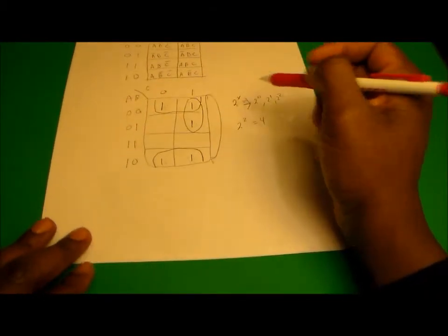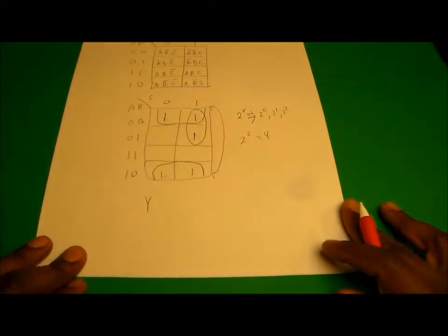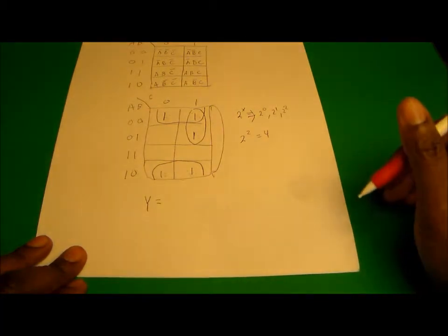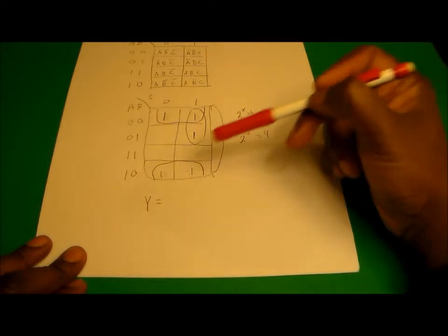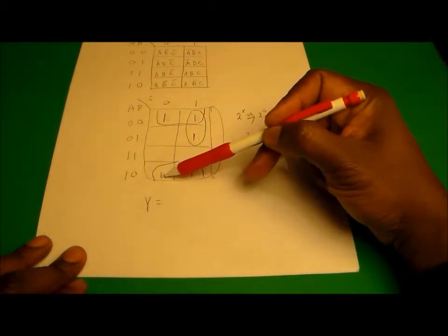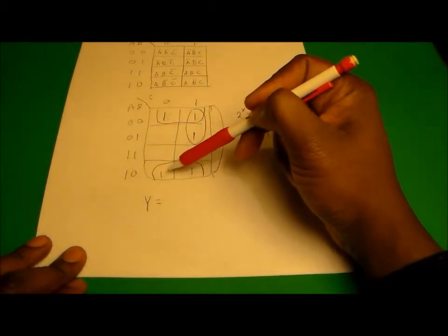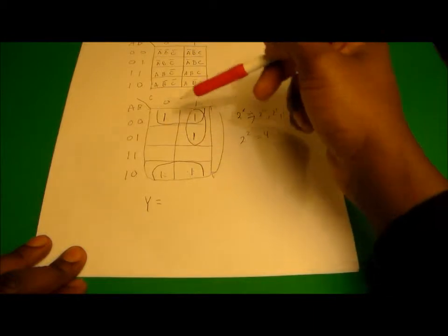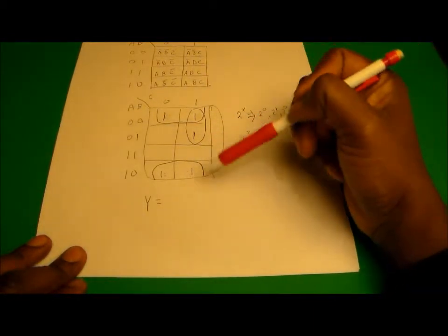So now in order to find our equation for our Karnaugh map here, or pardon me, for our circuit, the minimum equation using the Karnaugh map, what we would do is we'll say, okay, what must be true about all the ones that are inside these boxes, in each of the boxes. So let's start with the really big box first that has the 2 ones that are down here and also the 2 ones that are up here, making a total of 4 ones inside that box.